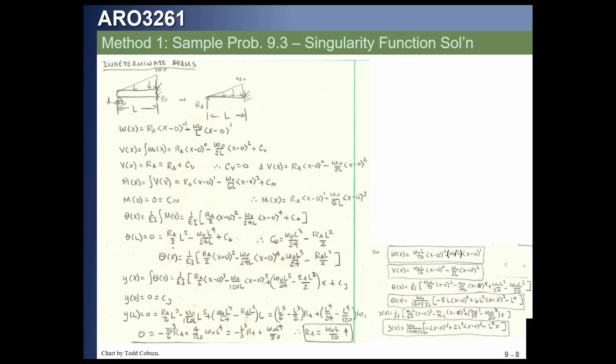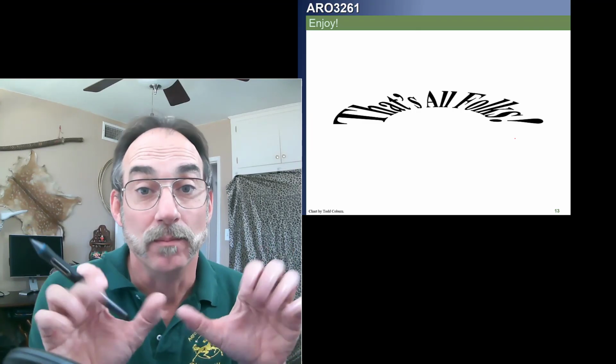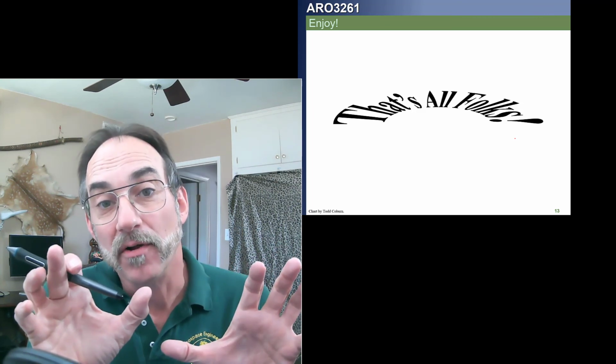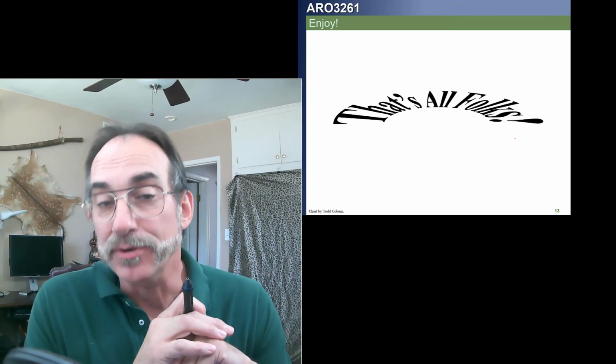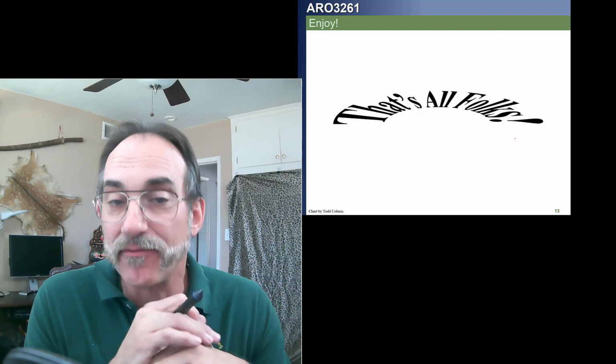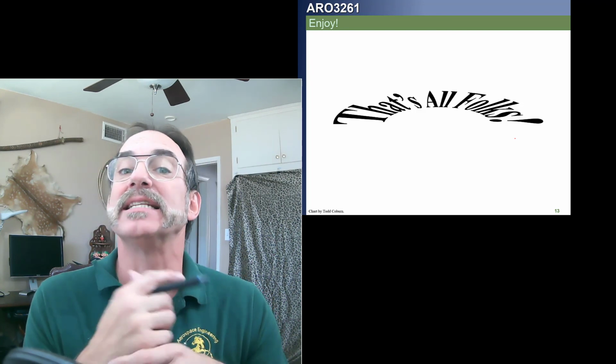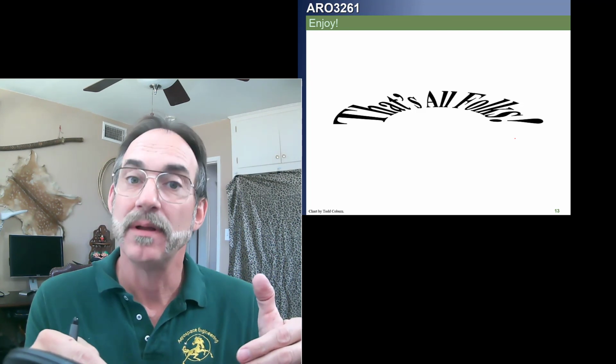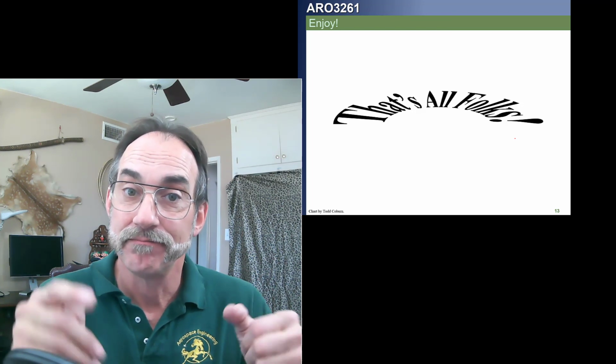Now, we can rewrite our equation of the beam, our loading, by plugging in the unknowns, our shear, our slope, and our deflection, and solve for any other terms we want. So, that is how we solve indeterminate beams, using the exact same procedures we did for determinate beams, except now we're imposing additional boundary conditions. Enjoy.